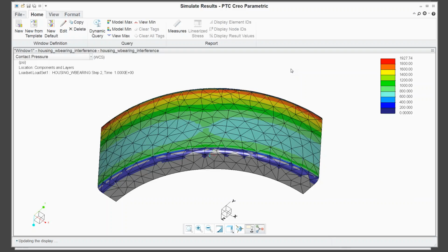One technique for doing that, by the way, would be to make a merge part where you can actually have interference between the parts and it will resolve them. If there is interference and it is not a contact issue, then there's no problem. The parts simply occupy the same volume, and that's okay. So that is an issue. It is very common to have to do tweaking to the model to resolve those kinds of issues. Now, we do have a tool in Creo called flexible modeling that can help you do that without having to go back and make changes to the parametric model. So I wouldn't say that it automatically deals with those issues easily. There are other products where you can put in a tolerance for merging mesh. This does not work that way.